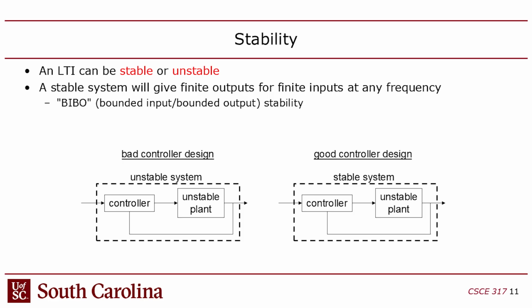And so the idea is that you have an unstable plant, you have a controller, which also may be unstable. Unstable plant, unstable controller, mash them together, and all of a sudden, surprise, the whole thing is now stable, right? And that's the goal of control system design. Now in this case, this is an open loop controller though. This doesn't have the feedback connection, notice. So what I've done is created an open loop control by just multiplying these two transfer functions together. Once you do that, then you can find the stability, the poles of the unified open loop control.